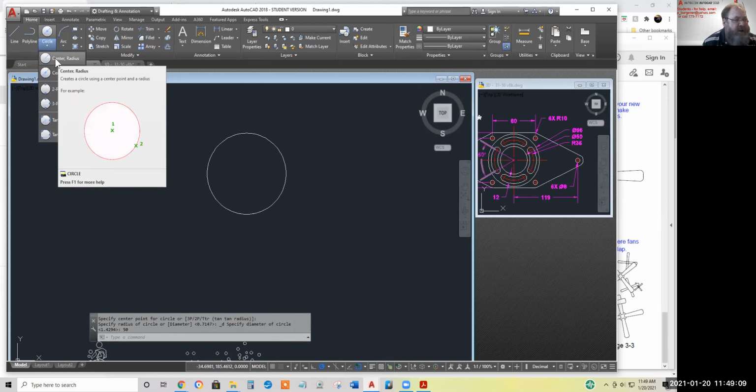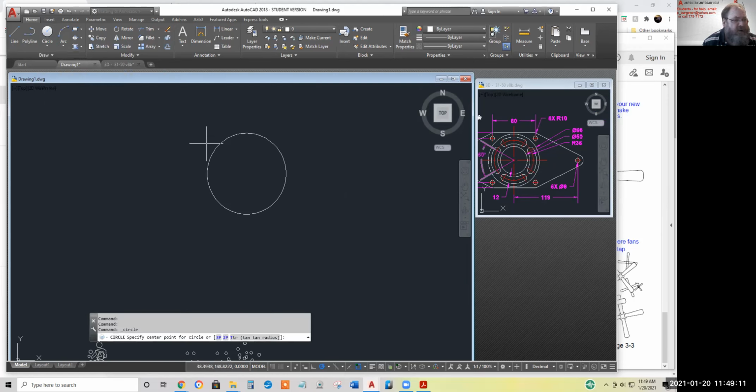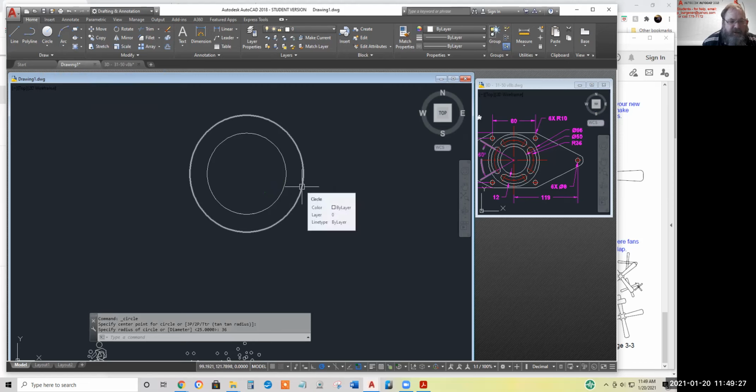So click the center radius icon, home in, gently slide on the circumference so AutoCAD knows you're looking at a circle. It'll highlight the center, and then type the radius of 36. Again, this is the red center line showing the center line of the jelly beans. We won't draw the red lines. That's coming up in a few weeks, how to draw line types and colors.